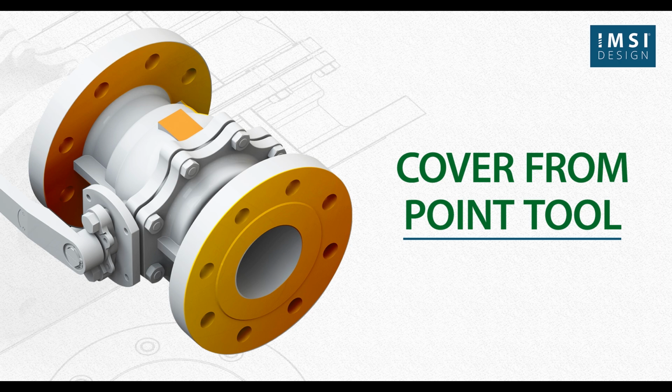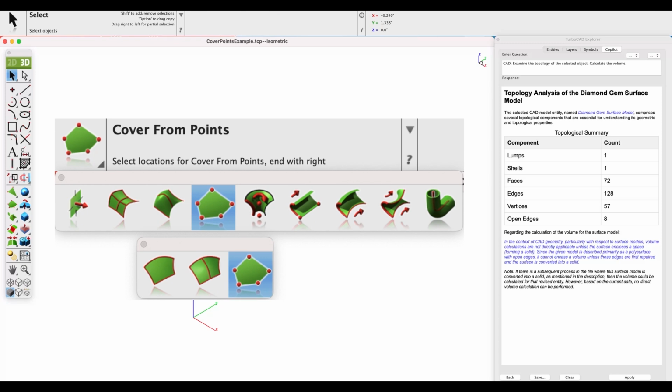Cover from Points tool. In this video, we demonstrate the Cover from Points tool. Cover from Points creates a surface from a collection of points representing the boundary of a surface. This will create a planar or non-planar surface depending on your point locations.